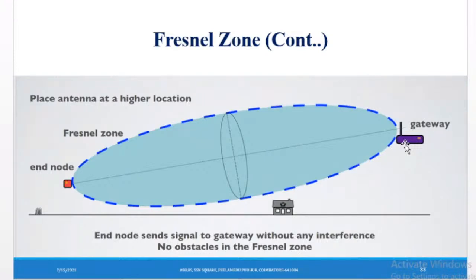So if I'm placing the gateway there, and after a week a heavy rain comes, on that day I'm getting some data loss. Why? Because the environmental factor automatically changes. Heavy rain reduces the signal. It also blocks the RSSI and all. So you will not get 100% data loss, but you will get some data loss.